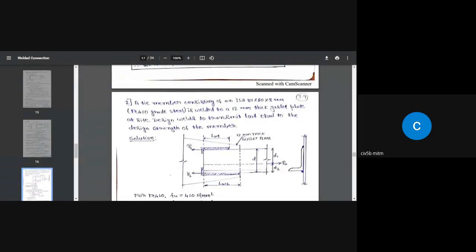And what is the thickness? 8 millimeter. So go to the third column where we see the thickness. We see the thicknesses 5 millimeter, 6 millimeter, 8 millimeter, and 10 millimeter. So ours is 8 millimeter thick. So the area of cross section of that is 978 millimeter square.